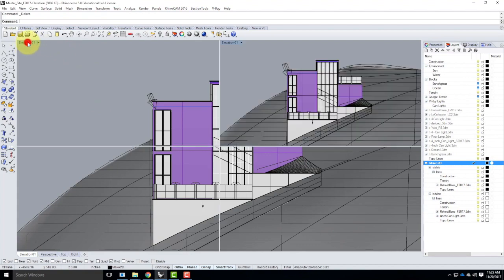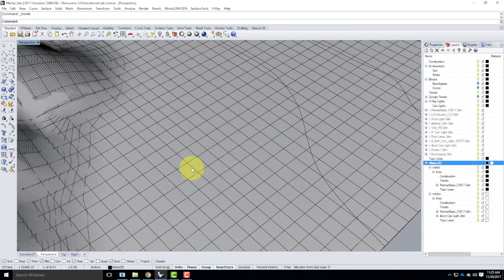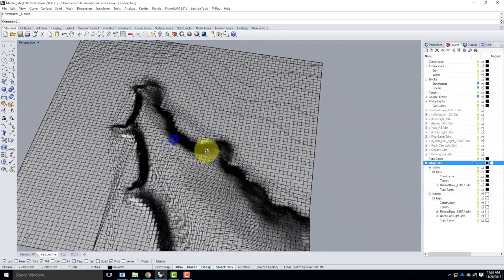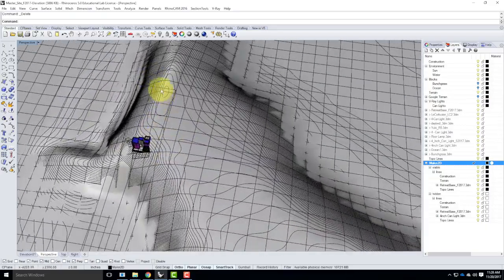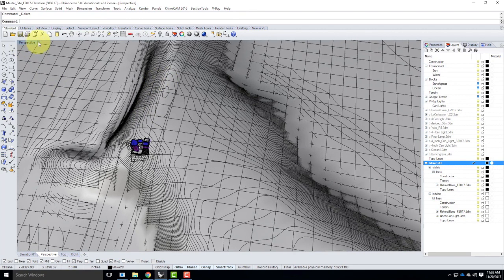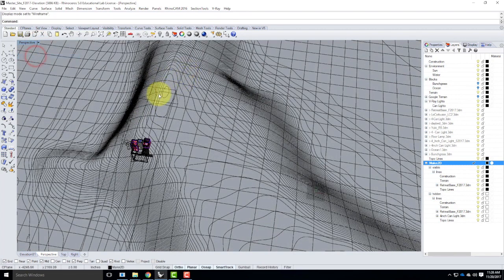So with the camera still showing, which it is, I'm going to go into the perspective view, and I'm going to create a box on my camera right here. Let me switch into wireframe so I can see. See these 3 points that are my camera? I'm going to use those right now to create a rectangle. So let me go into rectangle. I'm going to do 3 points. And I'll go from, turn off not, make sure point is selected. I'll go from point to right there. That gives me a quarter of the size of my view.